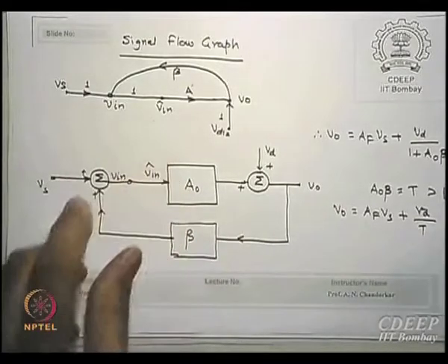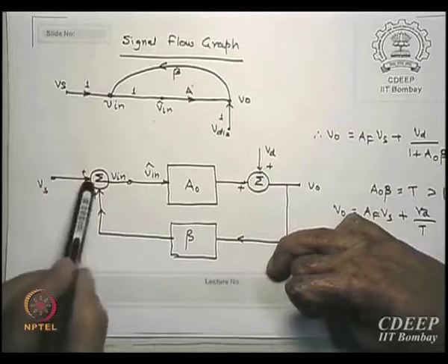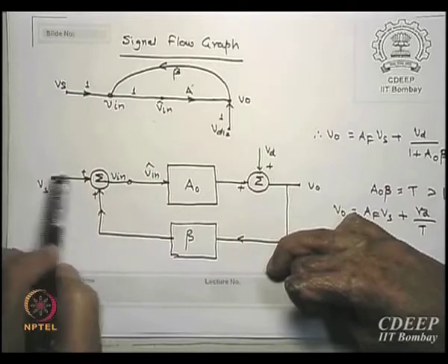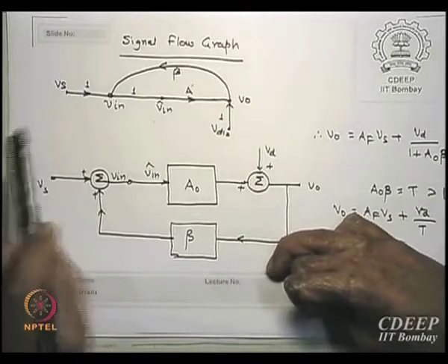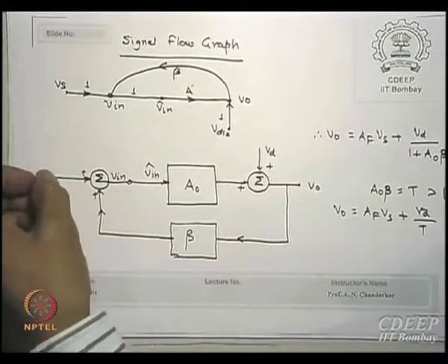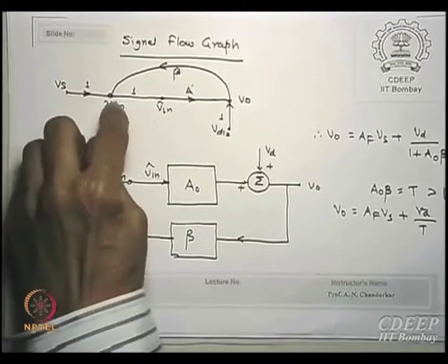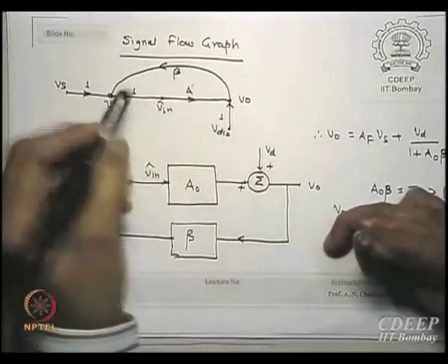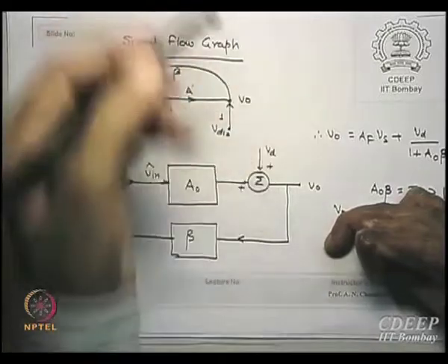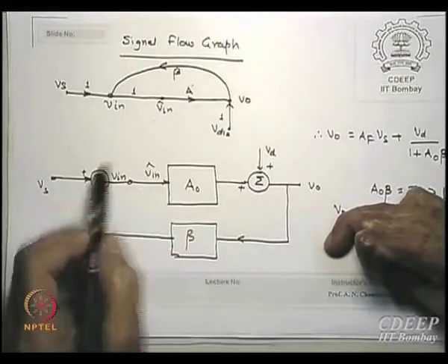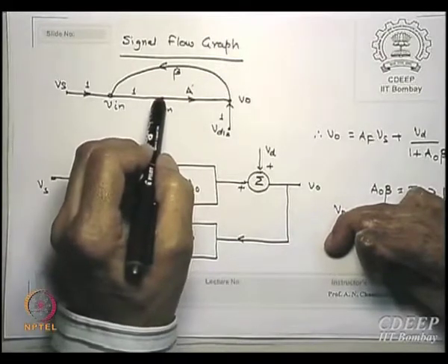Looking at the Vs to Vin, there is no network. Why has this one been put here? Because there is a direct transmission here. But if there is an Rs or some combination, this itself will have some gain there, less than 1, but Rs upon something. So from here to here the gain is 1 for now, so we write gain 1. We also don't say right now why I want hats, I will come back when I draw feedback full amplifiers. From Vin to Vin hat there is no change, it is the same connection. So we say it also has a gain of 1.